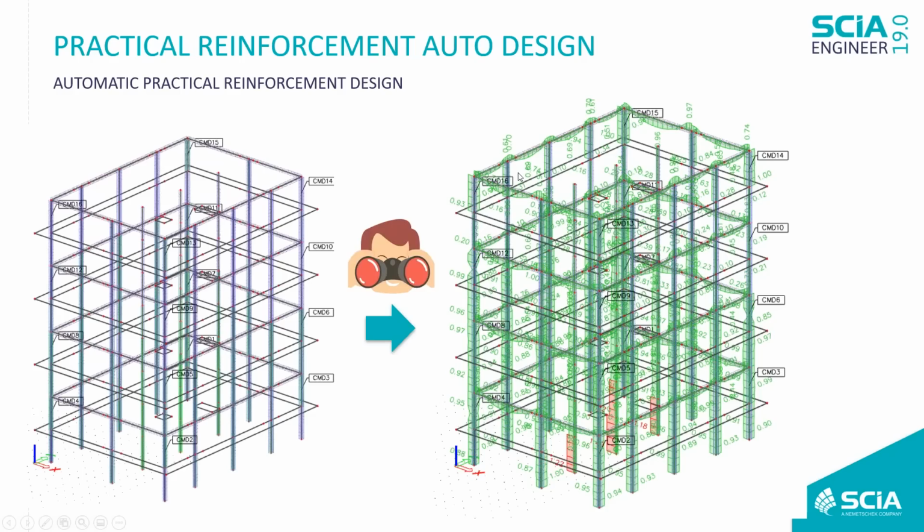Maybe you will say, stop Marwan, you are exaggerating too much today, because I cannot read the result here. In fact, my point from giving you this unity check is not to show you the value 0.96 here. What I would like you to see is the color. If the color is green everywhere, that's it. If you have some red spot, then you can easily find out where the problem is. And as you can see, I have a problem in this column, in that column, and in that column.